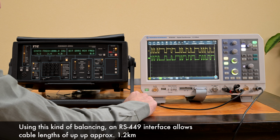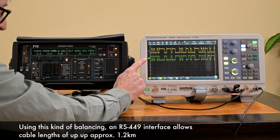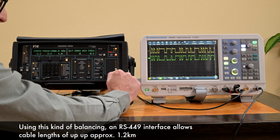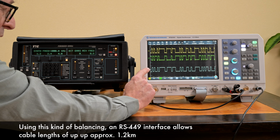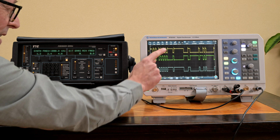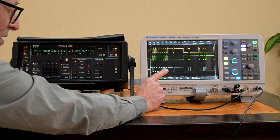So then normally the receiver basically would have a balanced input and would invert the second input and add it to the first one, and that would kind of cancel out all things. Actually, I did that in the scope right here, creating a math channel, which exactly does that. It takes channel 1 minus channel 2, and look at that. I get a channel similar in polarity to channel 1, but basically it's a much cleaner signal.